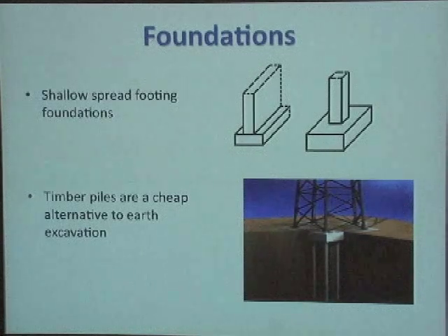The shops that were located on the east end, because they were more composed of a denser soil, we can use shallow spread footing foundations. But as for the restaurant, which is located more towards the water side of the site, we're also going to have to bring in a lot of fill, so we're proposing that we use piles underneath the foundations to ensure that it's a solid foundation for the restaurant.